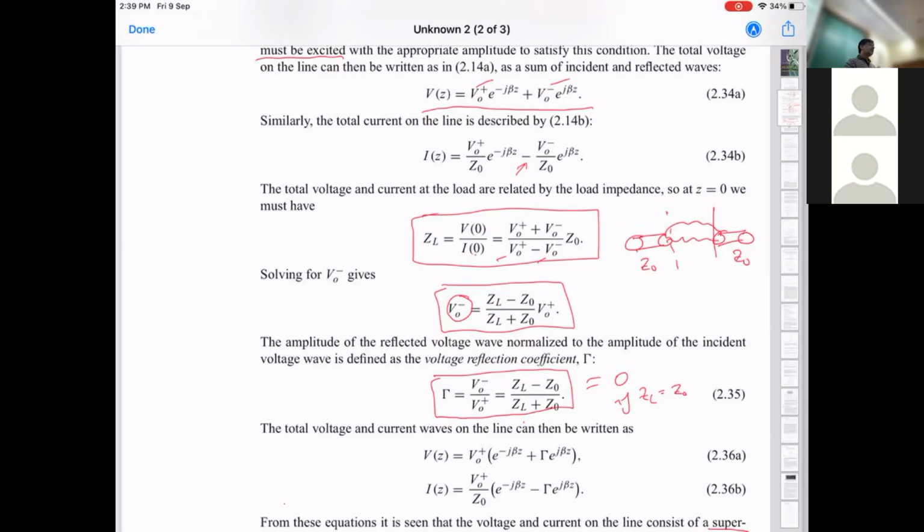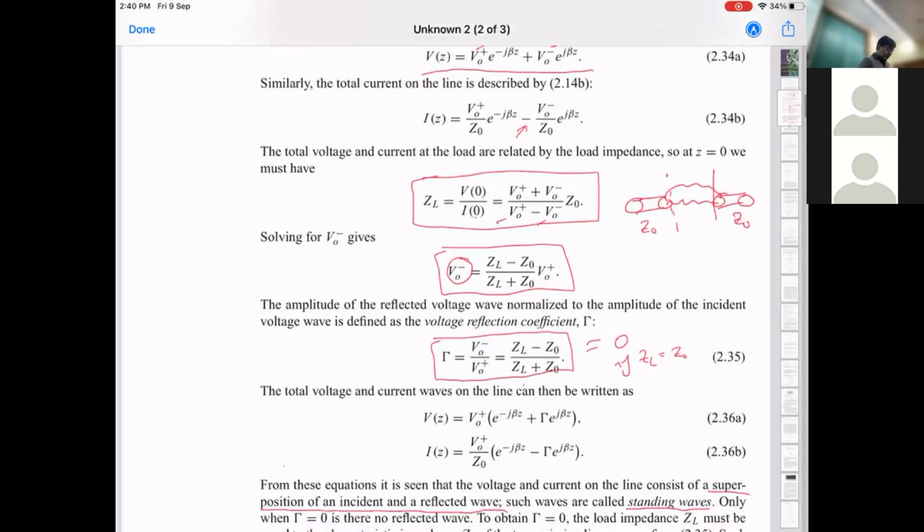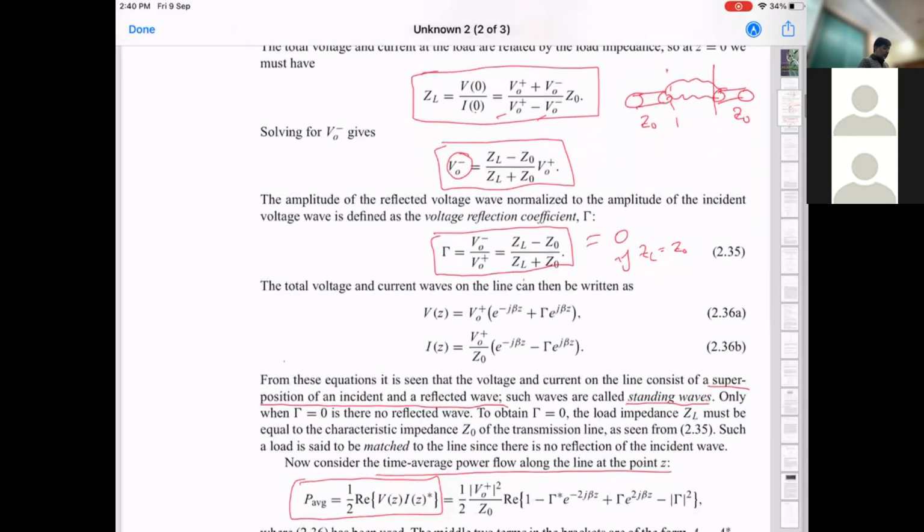So you need to have a sense for what is happening under different circumstances. But what this gamma tells you is very important information. Now, this reflection coefficient gamma is more precisely the voltage reflection coefficient. And I'm emphasizing this again because these quantities often are expressed in different units. So we're going to go through a few of these right now.